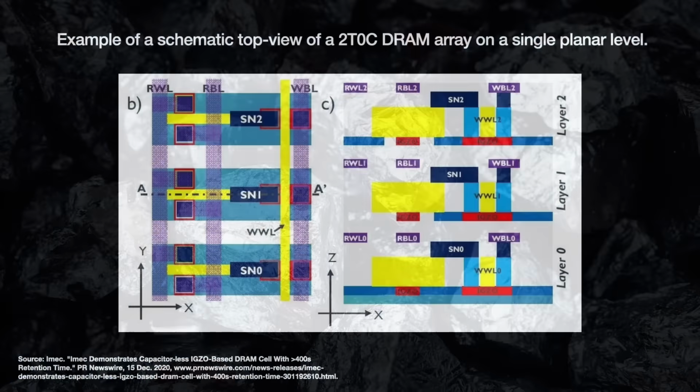So what is the catch, or catches? One is that we will need lots of contacts and interconnects to connect the read and write transistors. While we can optimize, this likely makes the cells larger. Some papers say you need a 9F squared cell, quite large. And while IGZO films being relatively easy to deposit makes their transistors more stackable, the cell is not totally flat. Irregular bumps due to all the interconnects and contacts can make it complex to build up large stacks.